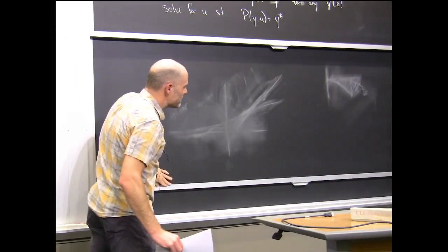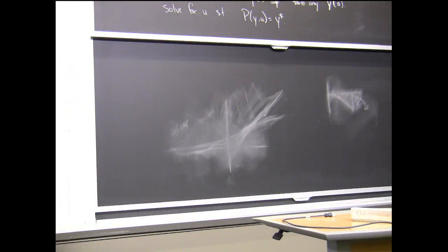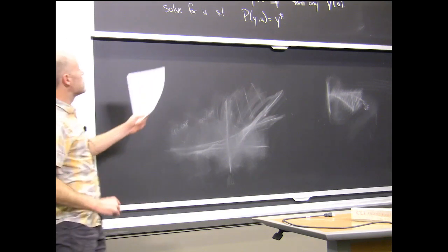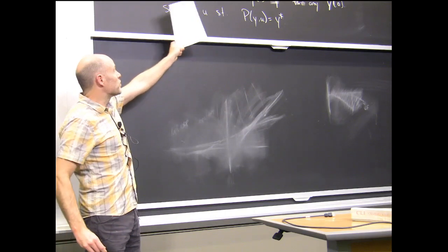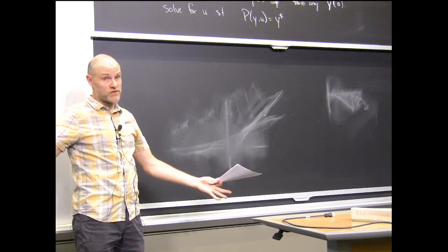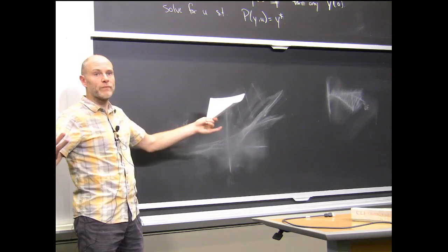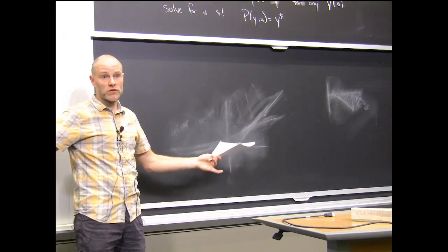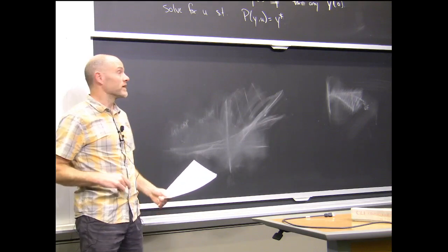It turns out there's a result that I just think is so cool. Yes, please. Are these two techniques only applicable to these slip models, or can they be used to stabilize any sort of model? The statement of linearizing a Poincare map is valid for any system. You could write an LQR controller. Just like for any linear system, you could ask, maybe it's stabilizable, maybe it's not. But for the stabilizable linearizations of Poincare maps, I would expect this to work in high dimensions for any sort of system. Getting a closed form solution of P is not always possible. We'll develop some of the tools to get around that.